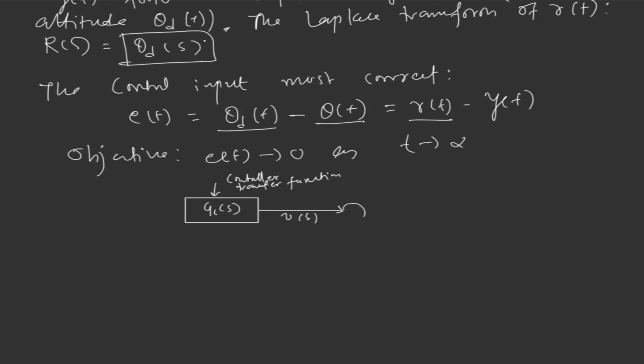and there is also a disturbance in the system. So the disturbance to the system is M_d(s), and the sum is going to the plant G_P(s), which is basically 1 upon I s square, the plant, and this is plus, and the output from this is Y(s).